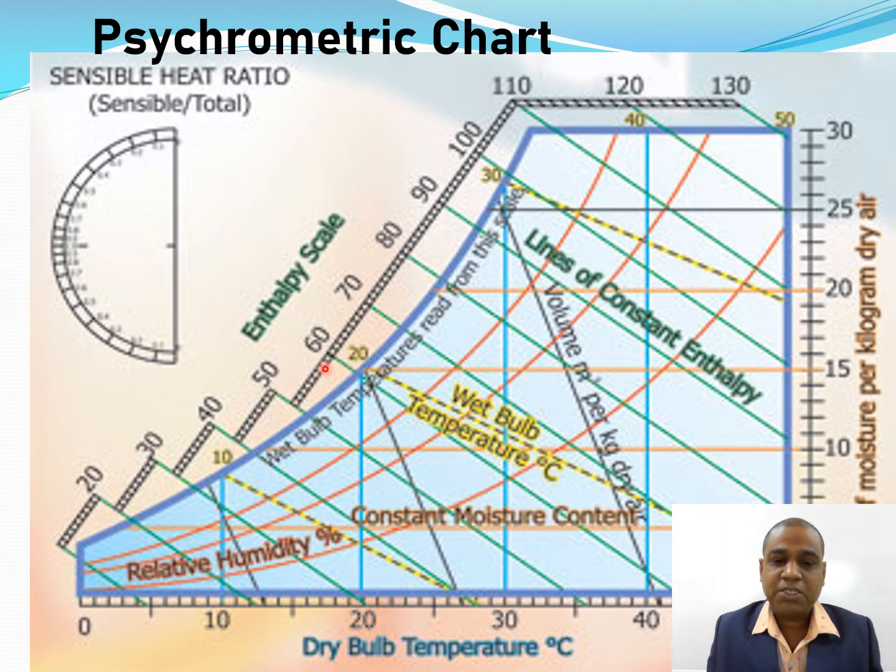That is the enthalpy scale. For example, it is not given as per the particular value. It is just the graphical representation for understanding. In the practical psychrometry chart, the specific enthalpy is written, that is kilojoule per kg of dry air.